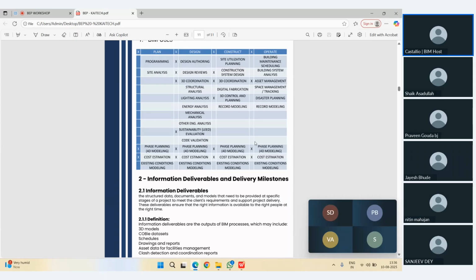Then we have the design review, then the detailed design happens, with stages like DD1, DD2, DD3A, DD3B. I hope anybody from a design background understands these stages. DD1 is kind of core and shell. DD2 is when not-so-detailed finishing level comes into the picture. DD3 is how the insertion will happen inside. All those are the design phases.